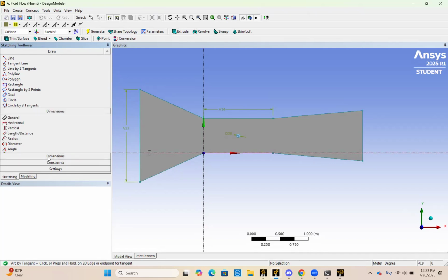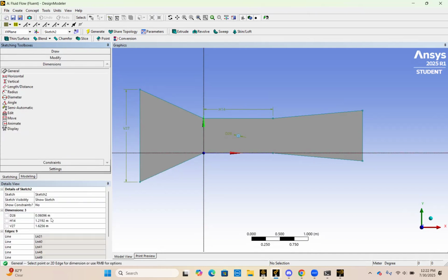To get your exact dimensions, you would press dimensions, then you can drag from the circle to give your diameter, or from any of these edges. It will give you the exact dimension, and then if you want to adjust this, you can just click and edit your geometry. So basically what I did was using dimensions to adjust the length or the diameter, whatever defines that element, that shape. So I basically have my wind tunnel here. Here's the inlet. Here's my outlet, right?